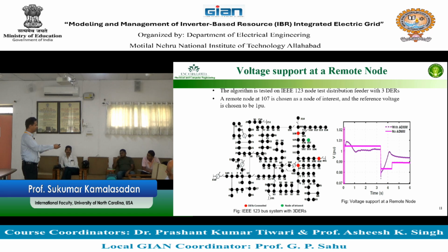When the regulator sees the light load, it will not tap. It may be tapping down instead of tapping up. But photovoltaics is delivering the power. If you tap up, what happens? The voltage goes up instead of going down. If it goes up, then the regulator will see an even lighter load, so it taps up again. Finally, it taps up and goes to positive feedback, and it goes to infinity. So that also can happen. But anyway, this one right here will not do anything.